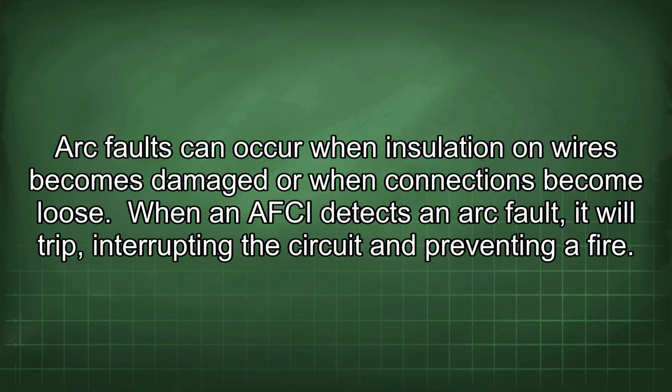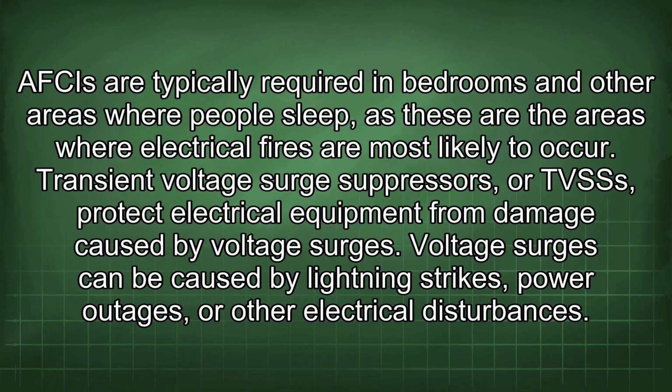When an AFCI detects an arc fault, it will trip, interrupting the circuit and preventing a fire. AFCIs are typically required in bedrooms and other areas where people sleep, as these are the areas where electrical fires are most likely to occur.